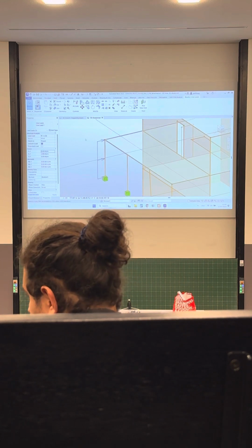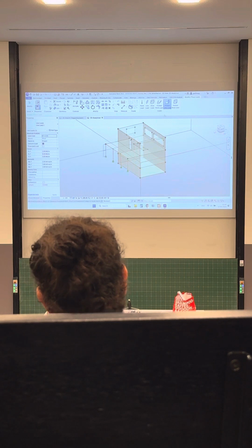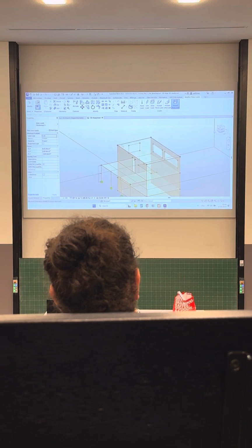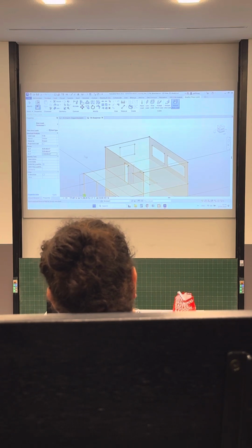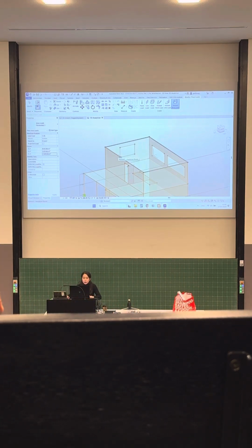And the same goes for other things, like let's check hosted area load. Let's create a snow load on this floor, on the upper floor. And for example, it already automatically gives us some values. But yeah, let's just play around. We just choose the panel that we would like to host it.